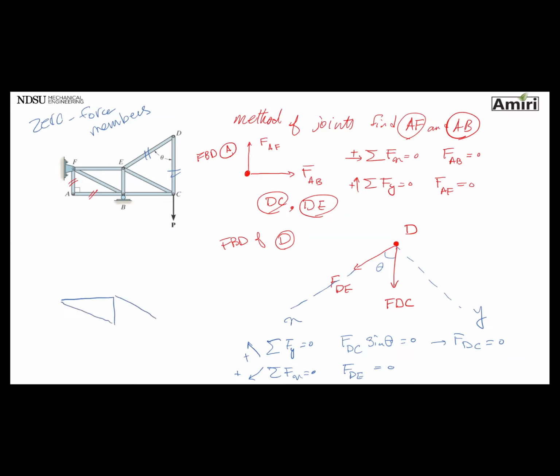Okay. So my truss is going to be, oh, sorry. I can remove those two as well. So my truss is going to be like this. These two trusses are exactly the same as far as loading is concerned. Although there is a force applied at pin C, this member DC is not carrying any of that load at all. So I can just remove them.